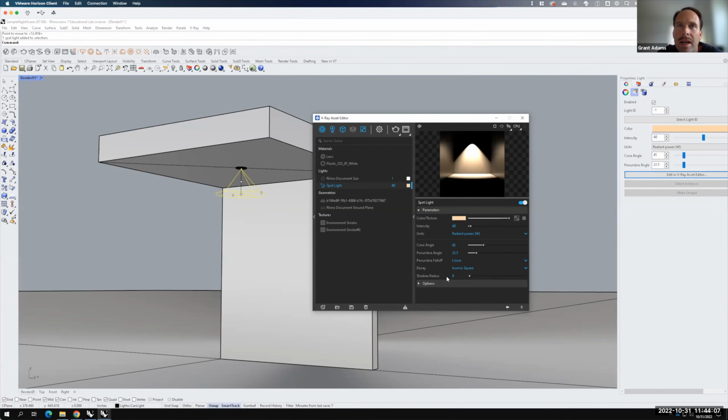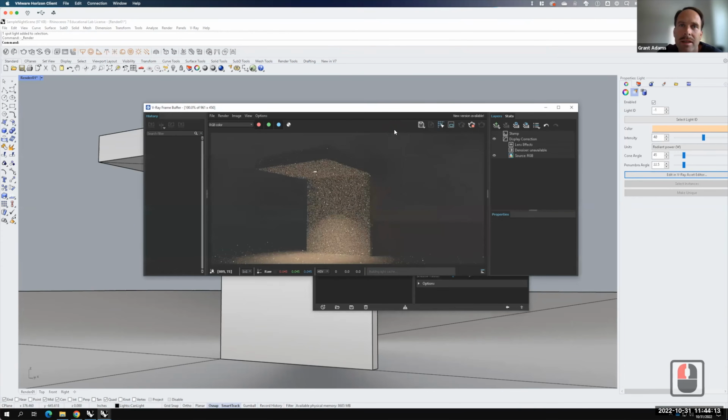And so let's go ahead and do a test. A lot of V-Ray and lighting conditions is to just jump in and do some tests. You can see now, when I cast the light, that there is actually a light in the scene, and it's mimicking as if the light was coming from the center of this little roof overhang. It's casting a nice little cone on the wall, and it's casting a circle down on the ground, which is what the light would look like if we had that kind of a light in this scene.